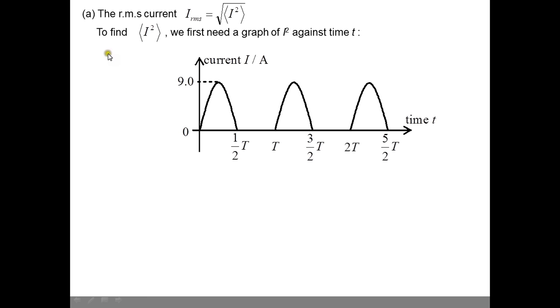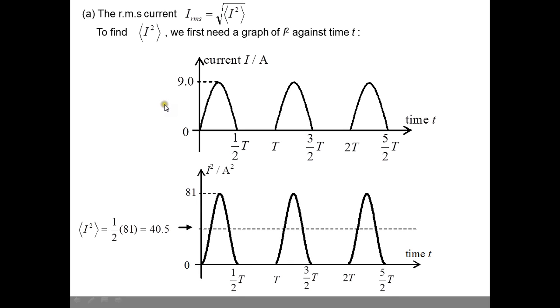So here, to find the root mean square current, we should first find the mean square current. So what you do is that you square it. Remember in the previous video, when you square a sine wave, you get a sine square wave, and it is actually rather smooth at the bottom. It's not pointy, it's smooth. However, because you remove the other direction of the current, the negative direction current, the sine square for those parts will also disappear. So by squaring it, you get this.